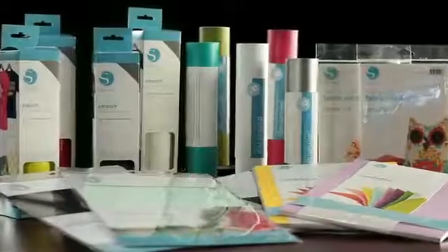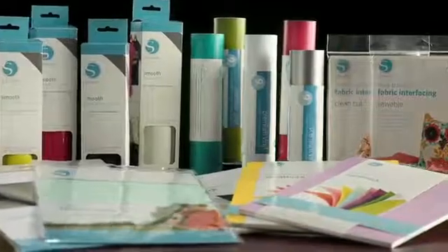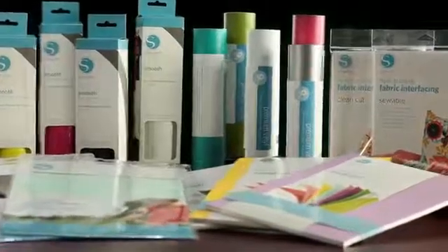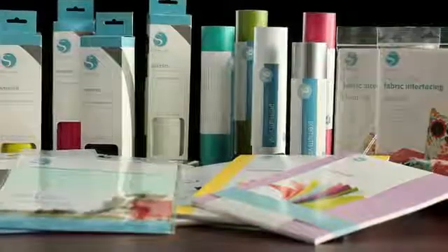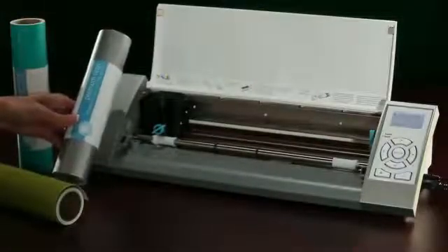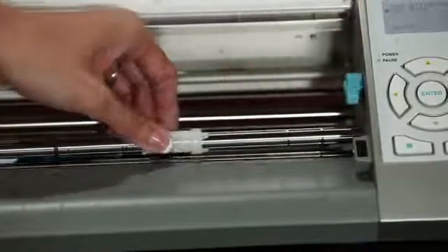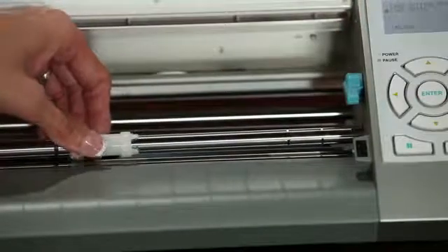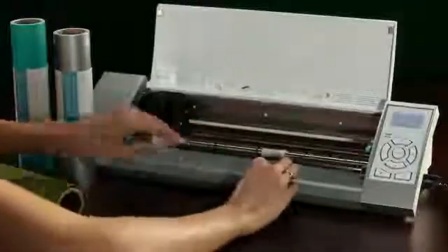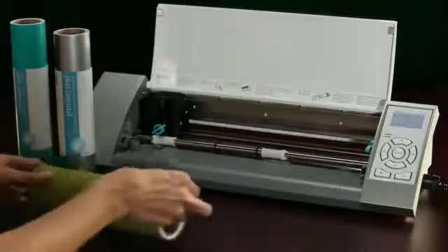Of course, Silhouette offers so much more than the ability to cut cardstock. The Silhouette CAMEO can cut vinyl, fabric, heat transfer material, magnet paper, and much more. Some of these materials, like adhesive vinyl, have their own non-stick liner. These materials don't need a cutting mat in order to be fed into the machine. Adjust the pinch rollers to fit your media on the CAMEO by unlocking the main roller shaft and twisting the right hand roller. Special notches mark where the A4, letter, 12-inch and 13-inch sizes are.